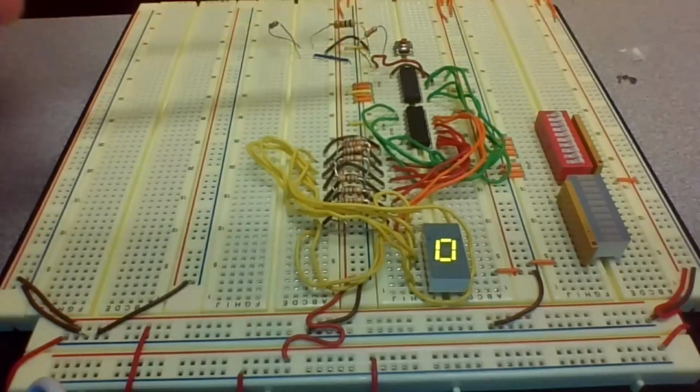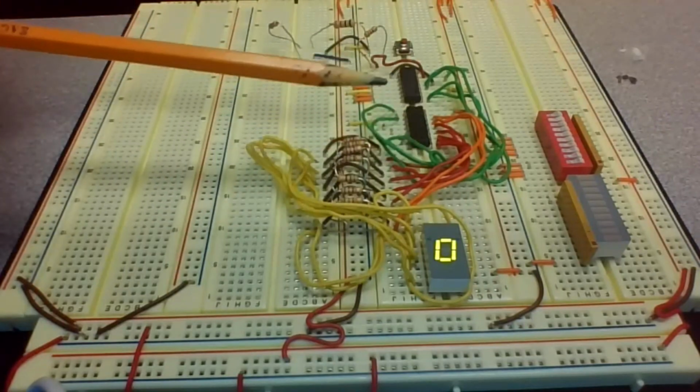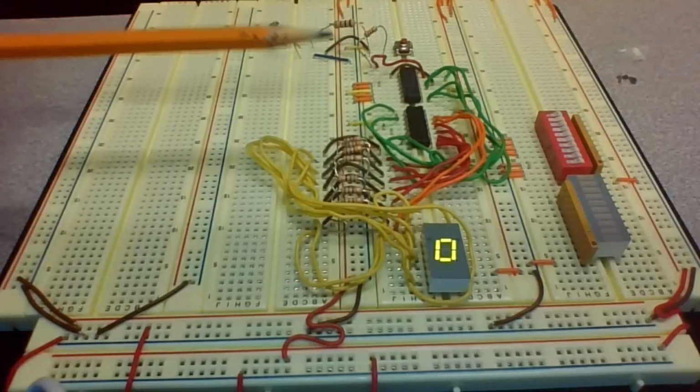So we have the bouncing switch problem. Sometimes whenever you push and release, it is possible it counts more than 1, which is fine, because bouncing means whenever you push and release the switch, until the switch gets to its stable condition, it usually jumps around 0 and 1. Same thing whenever you release it: it moves from 1 to 0, and until it gets to the stable condition, it jumps around 0 and 1. That's the reason whenever you push the switch, sometimes you see it count more than 1. The reason for that is the bouncing switch.